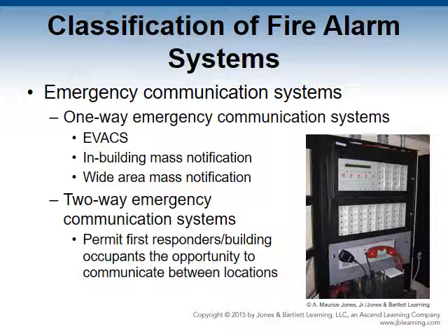systems and media. In-building emergency voice alarm communication systems, EVACs, provide first responders with a notification tool to manage occupant evacuation. It can be standalone or an integrated part of a facility's fire alarm system. Primarily installed in high-rise buildings with large occupant loads and special amusement buildings, they provide a voice message notification as well as visual notification, which typically consists of strobe lights.